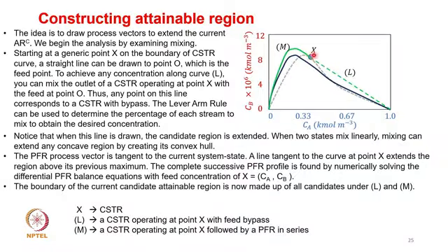So here is the CSTR operation, and anywhere you want to achieve, you have to add the feed. Which essentially means that anywhere along this line, the outlet of the CSTR operating point is mixed with the feed point O, which essentially means that it is a CSTR with a bypass. Again, you can use the lever arm rule to find out wherever you are standing on this line.